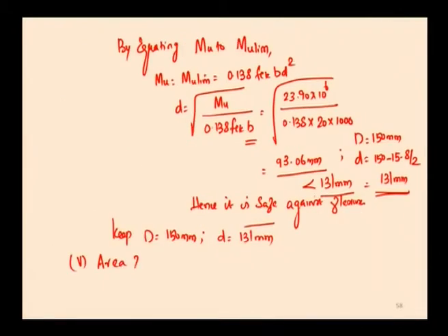area of reinforcement. First, in the case of a one way simply supported slab, there are two reinforcements, one is main steel, another one is distribution steel. The main steel is found from the bending moment. Since we have increased the depth of the slab, this slab is automatically an under reinforced section, normally Mu is less than Mu limit. So, it is designed as a singly reinforced rectangular section.